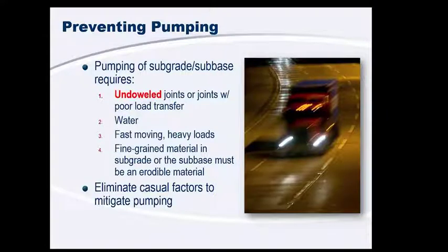And if you don't have fine-grained material that's erodible, then you don't have anything to erode. So this whole pumping action can really erode your support system and basically destroy your joints. So the main way that we combat this is through doweling our joints and making sure that we have proper load transfer.